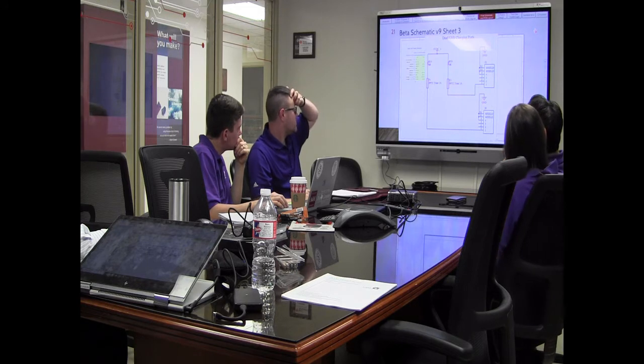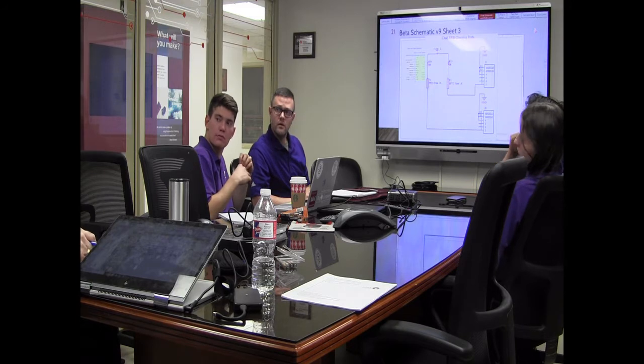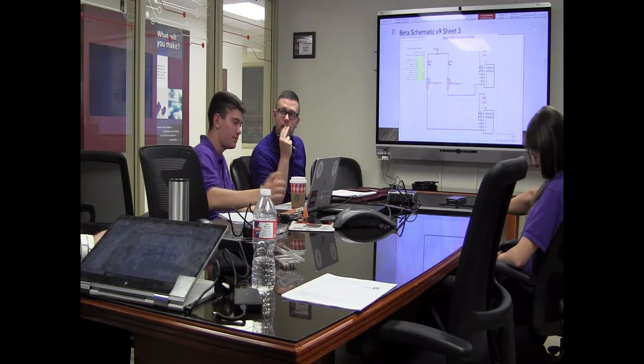Here's our dual USB charging ports with the PPTC fuses. So they'll go up to 1 amp safely, and it's just a simple. On those fuses, how long does it take at 1 amp to have them break? You have to look at the spec. They're supposed to be rated at operating temperature. If it's a 1 amp fuse, at 1 amp it should go infinite. But how long does that take? It was milliseconds on the stuff I was looking at. Really? It was very short. And then what's the reset time? Again, you have to look at the specs. Typically, I would think it'd have to cool down. It does, whenever it cools down, but they cool pretty quick.